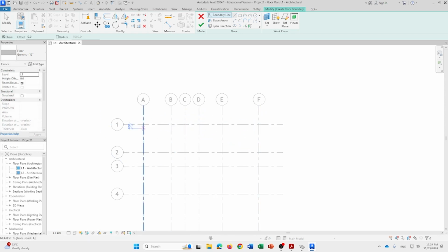Another purpose of these grid lines is that it allows us to snap at a certain point. So if you have certain dimensions, that's what these grid lines are useful for. I've drafted out a little floor plan. So that was what these lines are for. So it should make sense soon. But again, that's the line tool. We have our rectangle tool. So again, corner from corner. So if I start from this corner, go out to this back corner, it should create the outline for the floor.